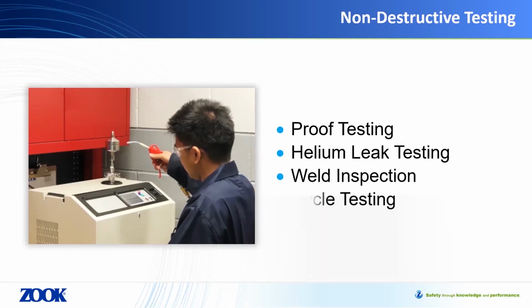One of the more common questions that we're asked is, how often should I change out a rupture disc, or how long will this disc last in service? This is a real challenge in the rupture disc industry, as cycle life is dependent on unique operating conditions. In order to help serve our customers' needs, we have the ability in-house to perform repetitive cycling on designs to provide real-life values.